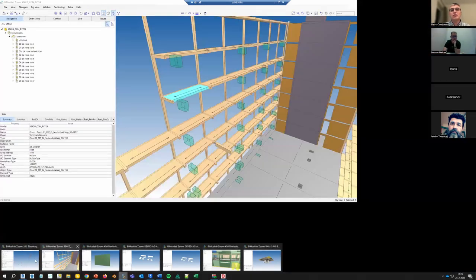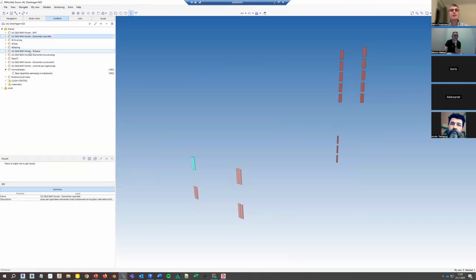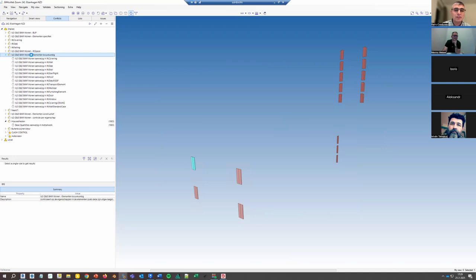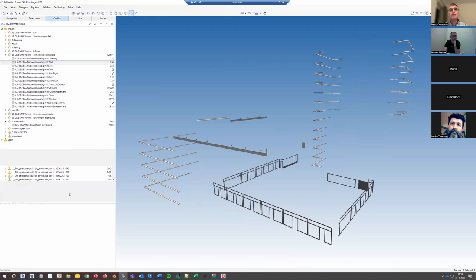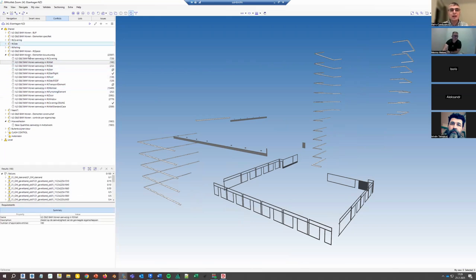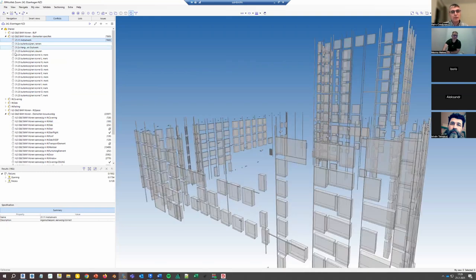They will not go and search in a custom property set for material, because they know we already have something called material, IFC material. They will not go and look in a custom property set for quantities, because we know we have Q sets, right? So this is the whole idea here. And when we looked at Menno, we saw that he had like 6 properties which were not able to fit anywhere else. But everything else is already defined by the IFC schema, right? So that's the whole purpose.